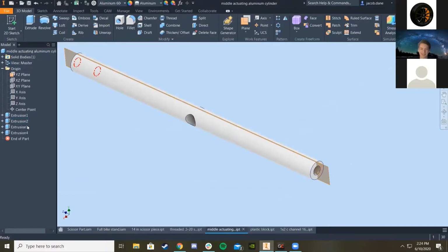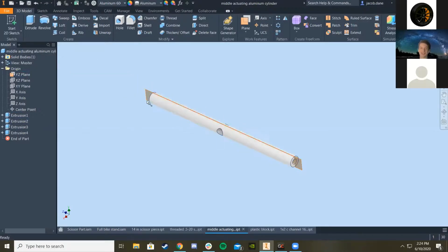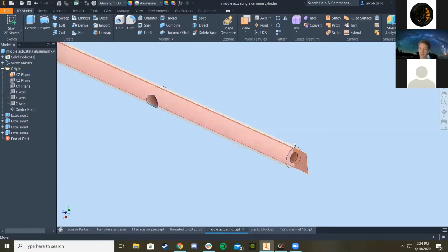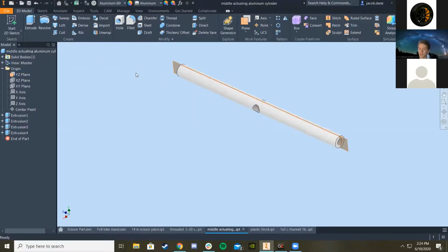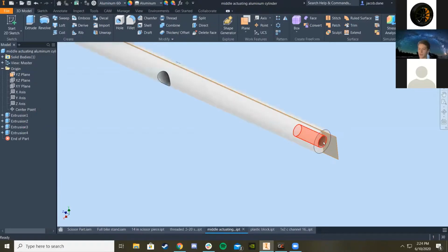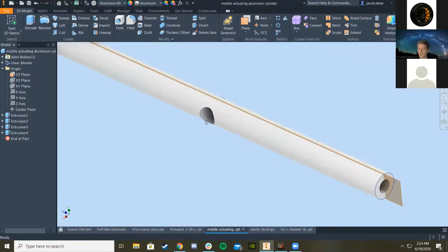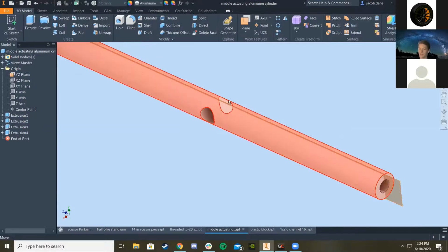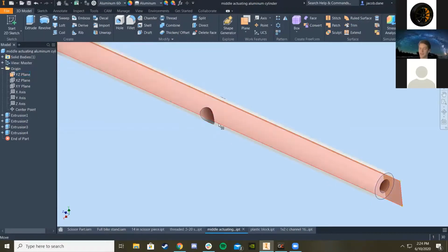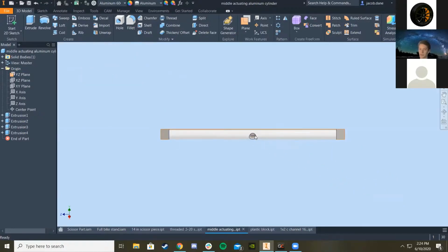Yeah, this is a 12-inch piece. I literally forgot to measure so many times. So it's a 12-inch piece, and then it's 0.75 diameter extruded through. And these holes are just 3/8. I just left an inch in. And then there's a hole just in the middle of it, which is 6 inches, and half of 0.75 is 0.375, and then just extrude it symmetrically so you get the extrusion through like that.